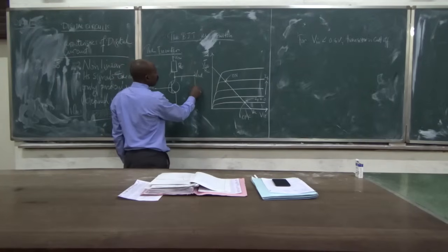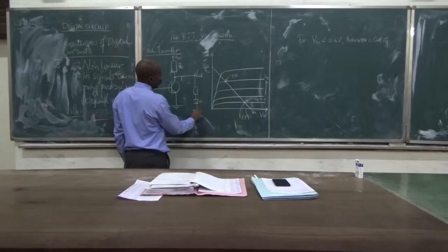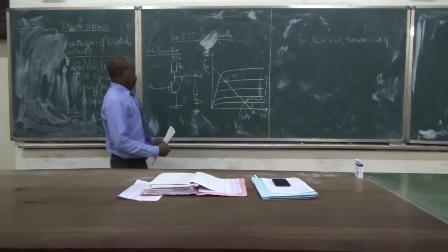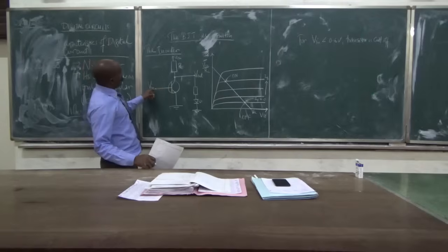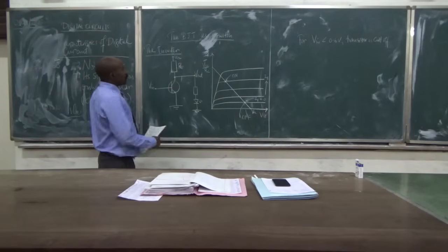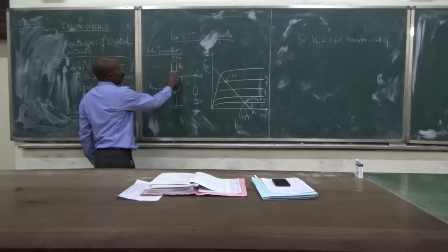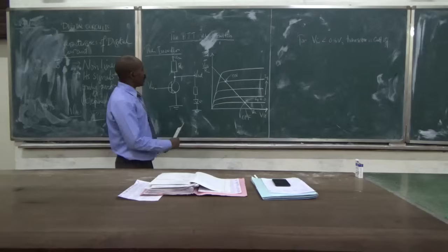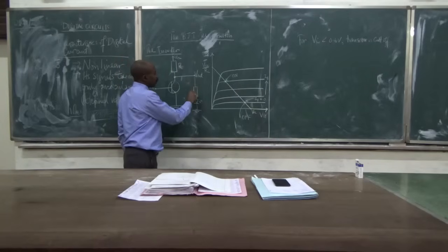So those who have done D1, you know that we have a LED protected by a resistor. And then when we ground it, it can be used as an indicator. So if you have V in less than 0.6 volts, then everything would flow this way, and nothing would bother to go through here.